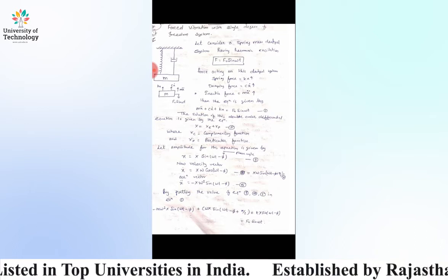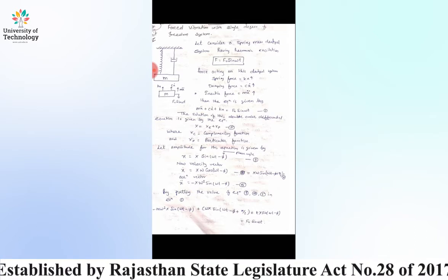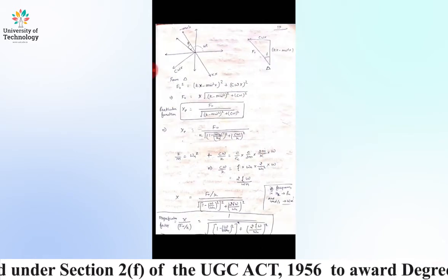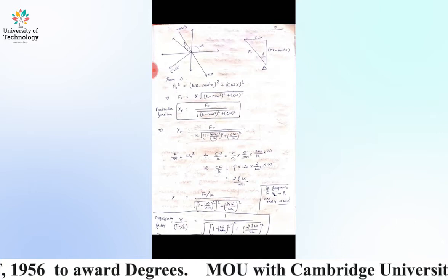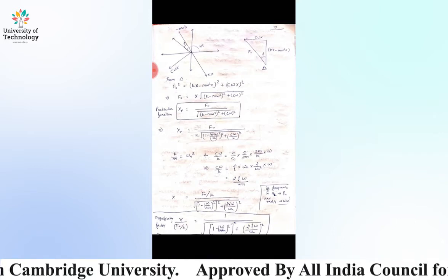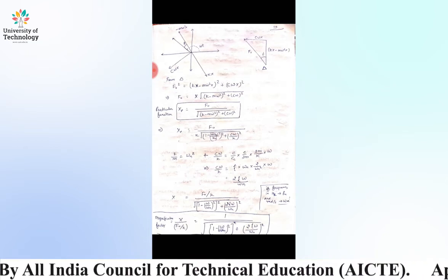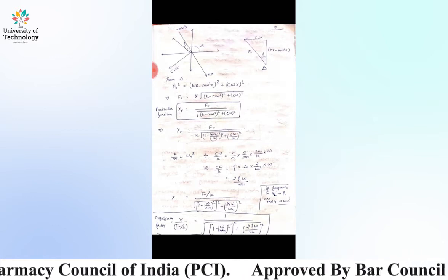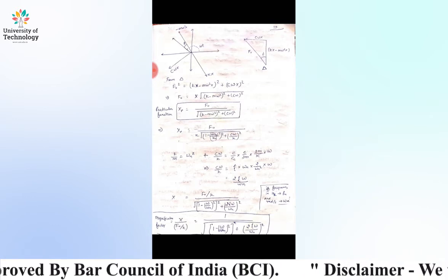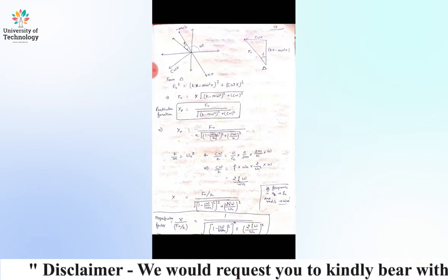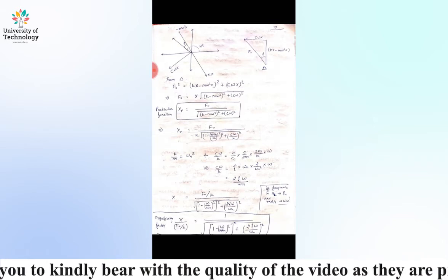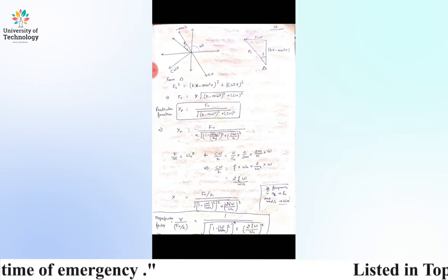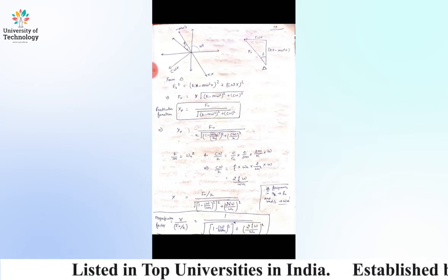If we put the amplitudes of the acceleration vector, velocity vector and the displacement vector in the form of vector representation, then we get this type of diagram, in which we can see the amplitude of the acceleration vector minus m omega square X and the opposite spring force kX leading by the angle phi, and the damping vector, or the amplitude of the damping force, is led by pi by 2 from the acceleration vector.